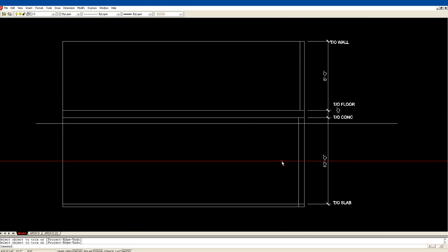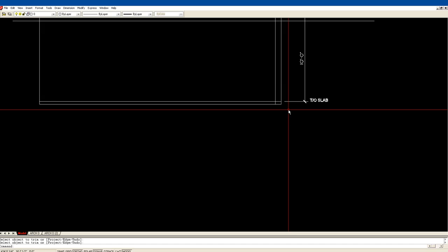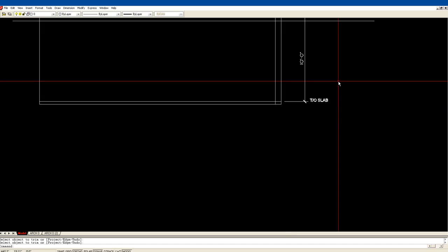Here is my concrete. Of course, underneath this concrete, to distribute the weight, you would have a concrete footing, and they pour it first. And typically, it's 8 inches thick, but 16 inches in width. And then it runs continuously underneath these walls.